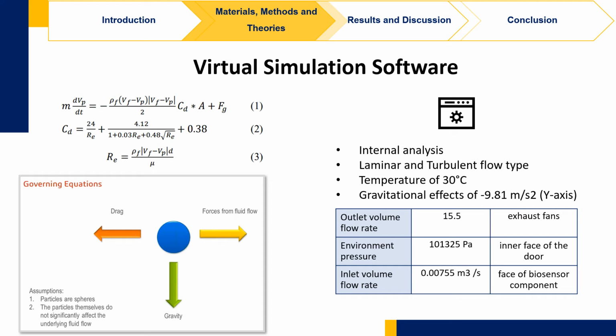An internal analysis investigates the flow through the structure. The flow simulation takes into account both laminar and turbulent flow types. The default settings were kept except for temperature and gravitational effect.